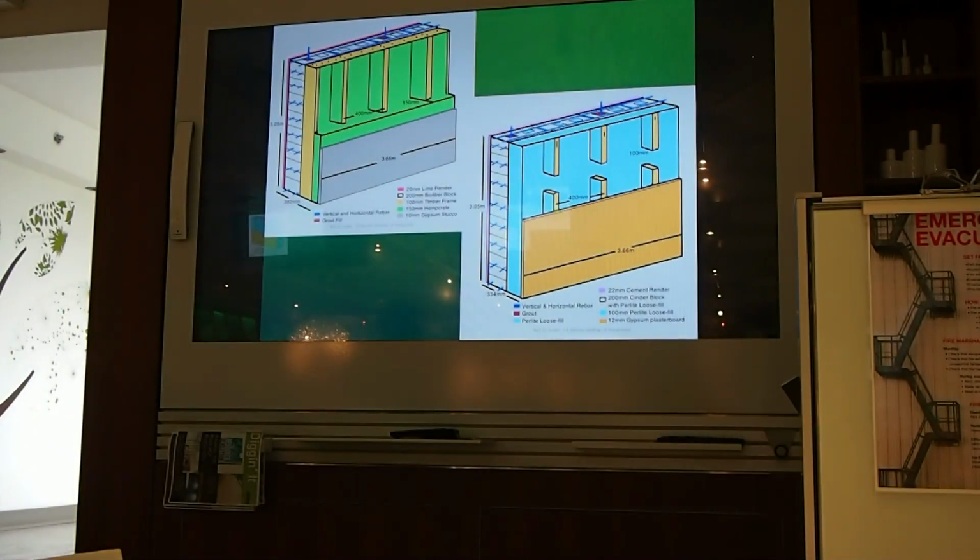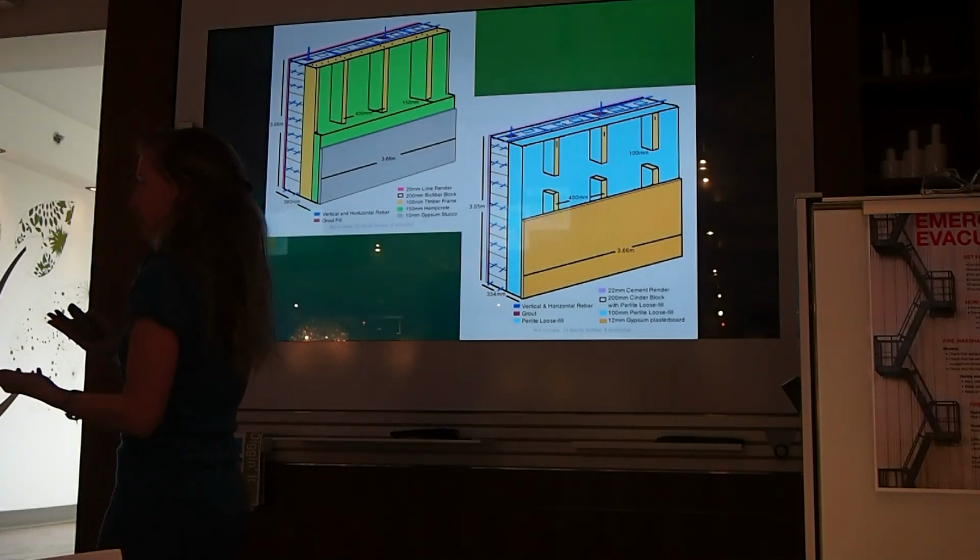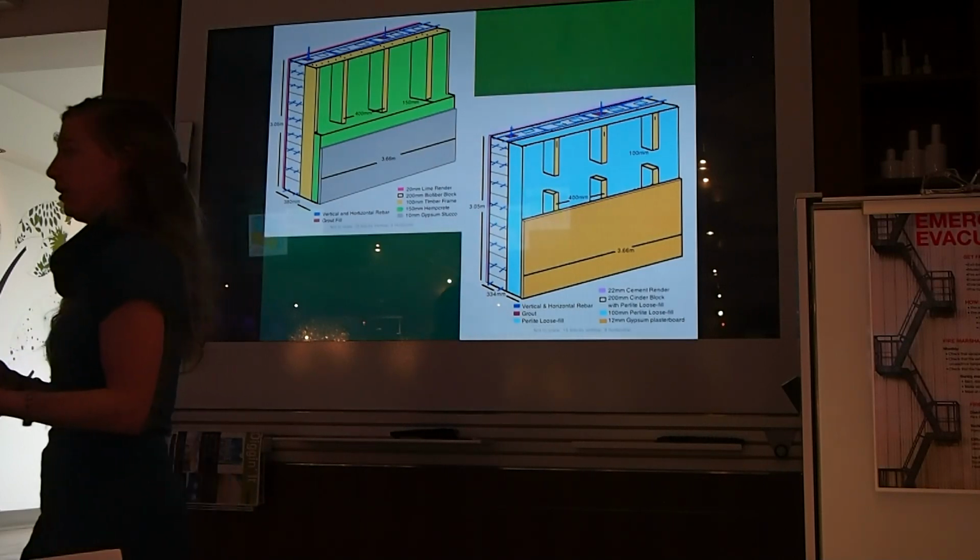These are very similar to cinder block in size, but they're lighter. The full thing is only 7.5 kilograms. But it doesn't have a compressive strength like cinder block does. But as I said before, it has the high R value quality. So therefore, since it doesn't have a compressive strength, it can't be a load-bearing material.